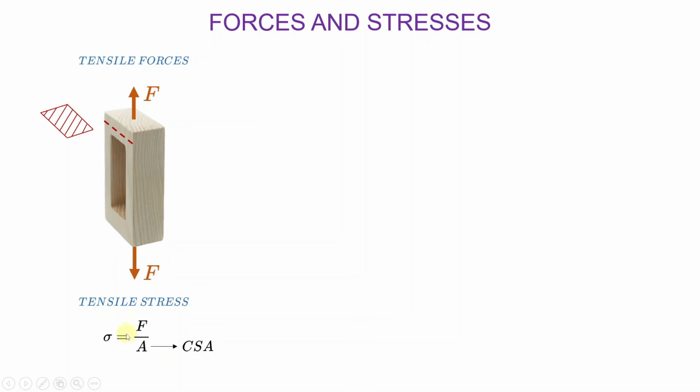Okay, so in this equation of stress, which is equal to the force divided by the area, here is the cross-section area. So if you were to calculate the stresses where this line is, the value of this area will be the area of this rectangle because that's the cross-section where the line is. But you may have to find the stresses at another location, for instance, where this other line is. Okay, so if you have to calculate the stresses where this line is, you can again imagine cutting through the object where the line is.